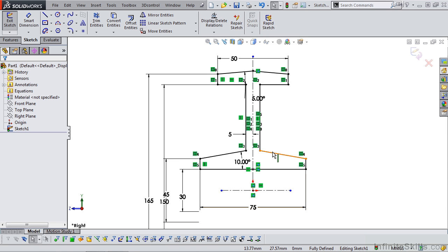Now before we conclude this, once again I want to mention that you could place your fillets in the sketch. However, when you are taking the CSWA exam, I believe it's better to keep your sketches simple. That way, if your mass does not match up with one of the choices, it's easier to go back and troubleshoot a simple sketch. I am going to add these radiuses in as a fillet feature.